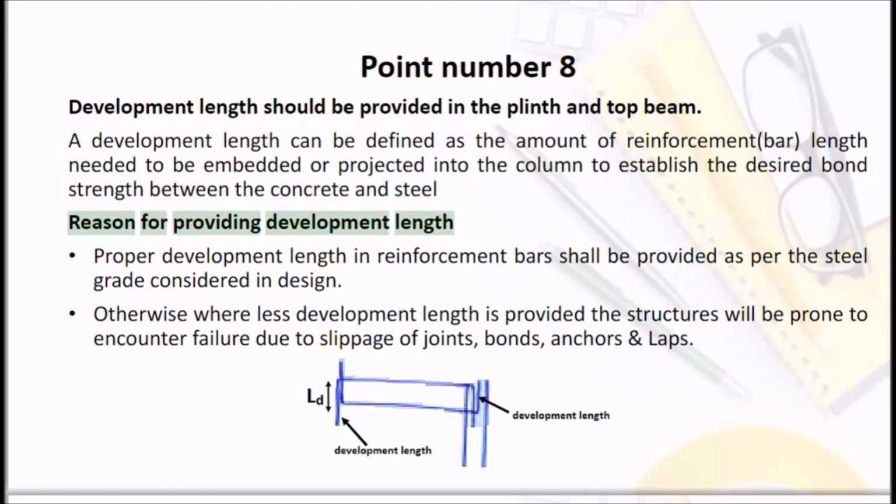Reason for providing development length: proper development length in reinforcement bars shall be provided as per the steel grade considered in design. Otherwise, where less development length is provided, the structures will be prone to failure due to slippage of joints, bonds, anchors and laps.